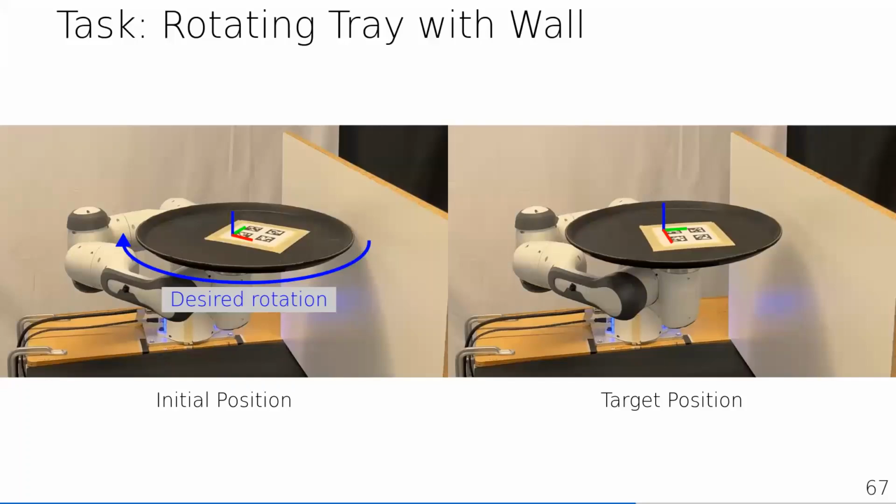Okay, so we introduced this task earlier as an example of a different task that an ideal method should be able to generalize to. To define this task more explicitly, the goal is to use frictional contact with the wall in order to rotate the tray. The tray needs to rotate again on the end effector, which means that it needs to reason about sliding contact as well. Because the tray is circular, this actually requires a lot of precision because the normal component of the contact forces is only pushing the tray off the end effector, and really only the tangential component of friction is helpful in rotating the tray.